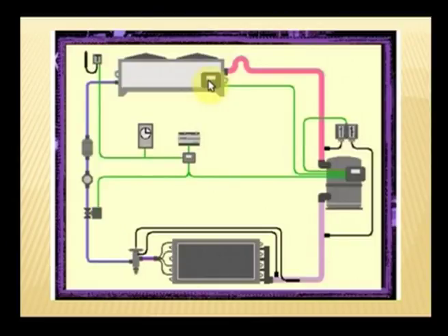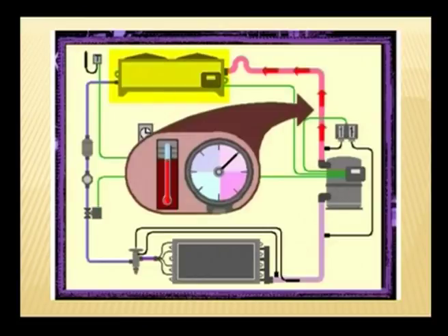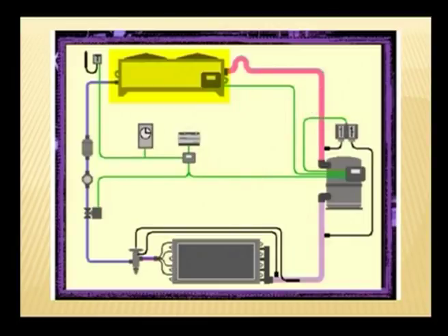In order to try to adapt to the variable flow of the refrigerant arriving at the compressor, some systems use multiple compressors. As the flow of refrigerant increases, the suction pressure increases, which in turn allows a larger number of compressors to start up. The condenser receives the gaseous refrigerant at high pressure and high temperature from the compressor. The function of the condenser is to condense the refrigerant in order to return it to the evaporator. The compressor and condenser fans operate simultaneously. It is the outside air that absorbs the condensation heat.